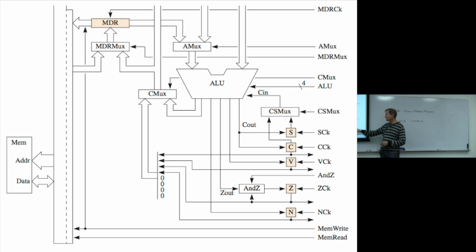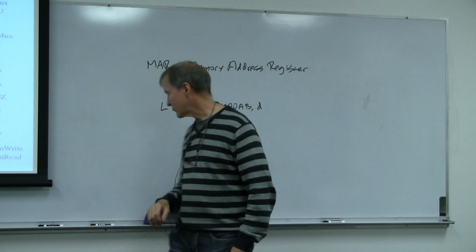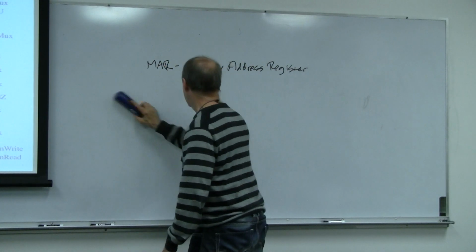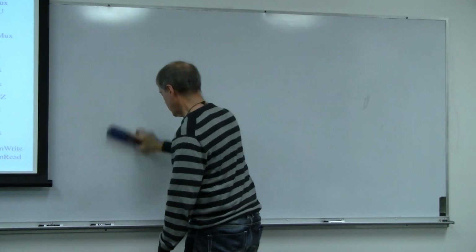And do you see that N is the same way? The N bit can be clocked in from the ALU, and it is also part of that right nibble that goes through the left input of the CMUX. But now here's a little complicating factor. What about this Z? Now do you remember here? Do you guys remember this?